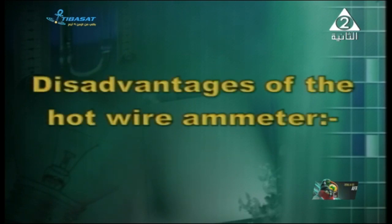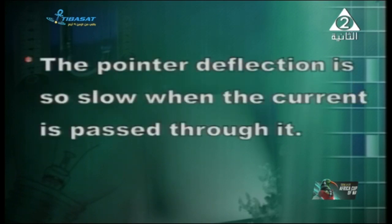And now talking about disadvantages of the hot wire ammeter. What are the disadvantages? As a matter of fact, one major defect here is that the pointer deflection is so slow when the current is passed through it. When the current to be measured is sent into the device, it takes time till the pointer comes to rest and measures. This is the first disadvantage. The pointer deflection is so slow when the current is passed through it.